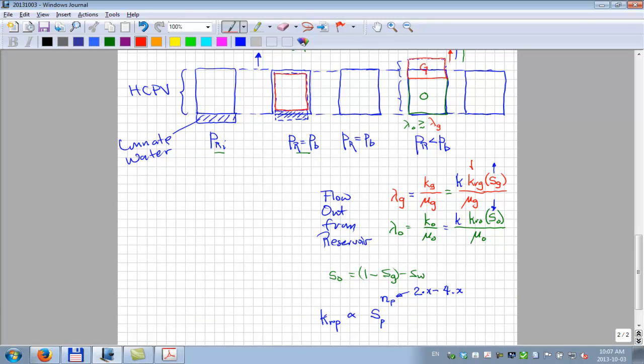The first thing is that the relative permeabilities are rock properties. And we don't know the rock properties when we do the PVT experiment. Even if we knew them, we would know that the exponent might range from 3 to 4 for a given reservoir. So there is not a fixed relative permeability relation.